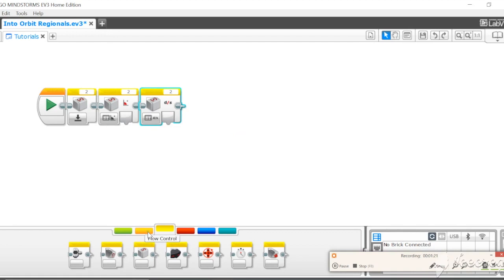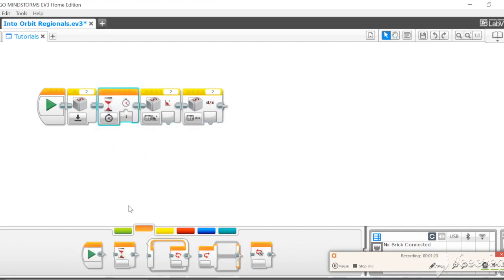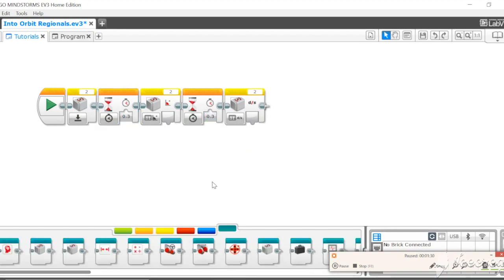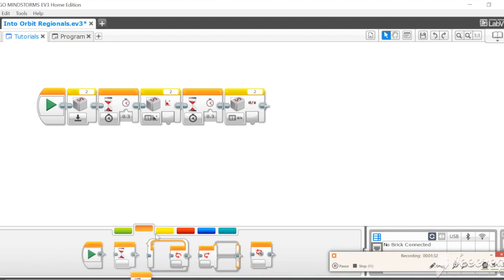But we do all these separately, so what you want to do is put a 0.3 second wait between these, as well as at the end. What this does is it helps the gyro to update and make sure that everything is at the value it should be. This does, however, take time, and it should be used sparingly if used for FLL. We recommend running it at the beginning of your program and using a regular reset anywhere else.